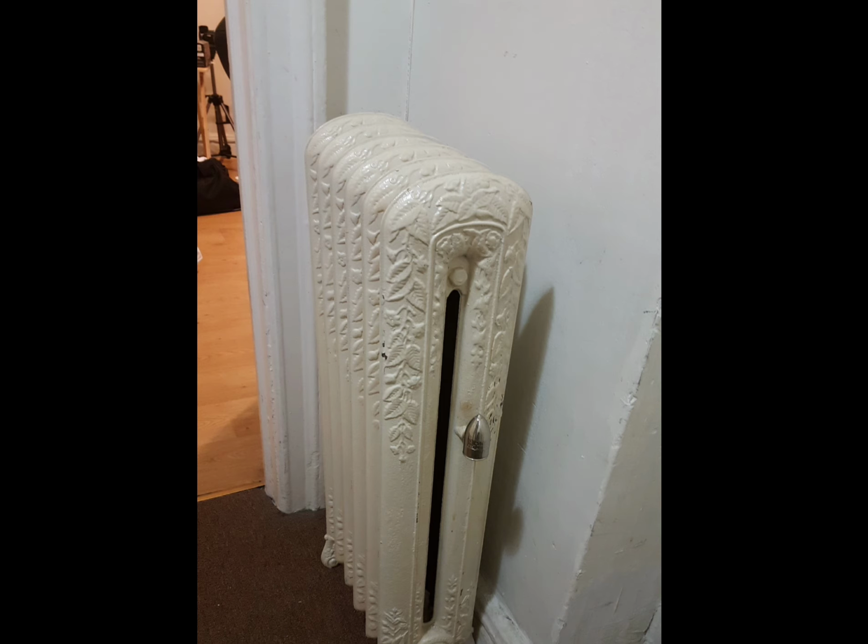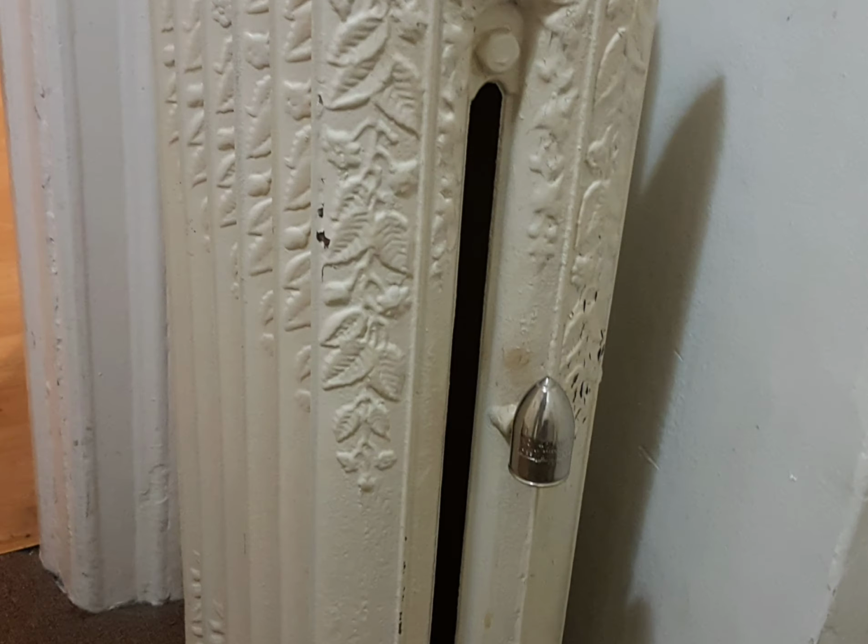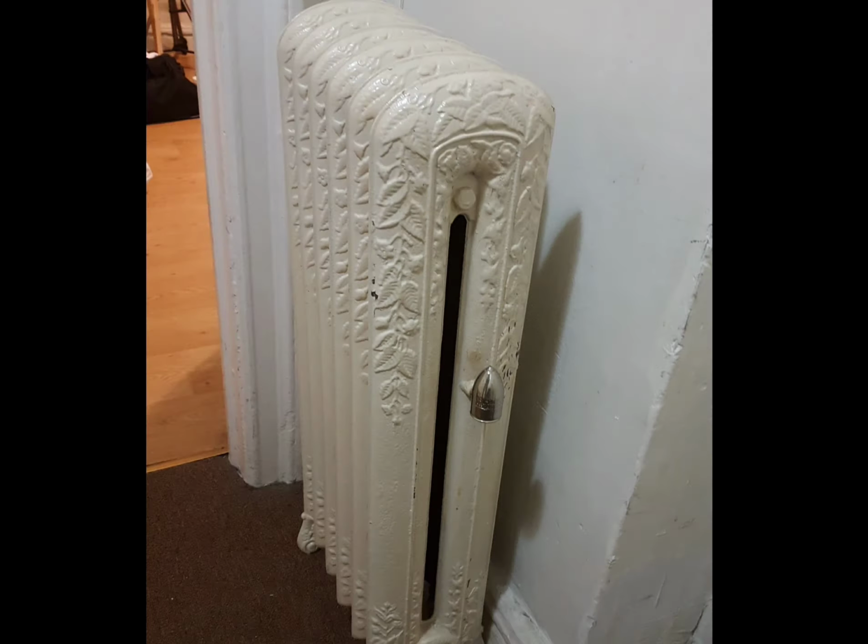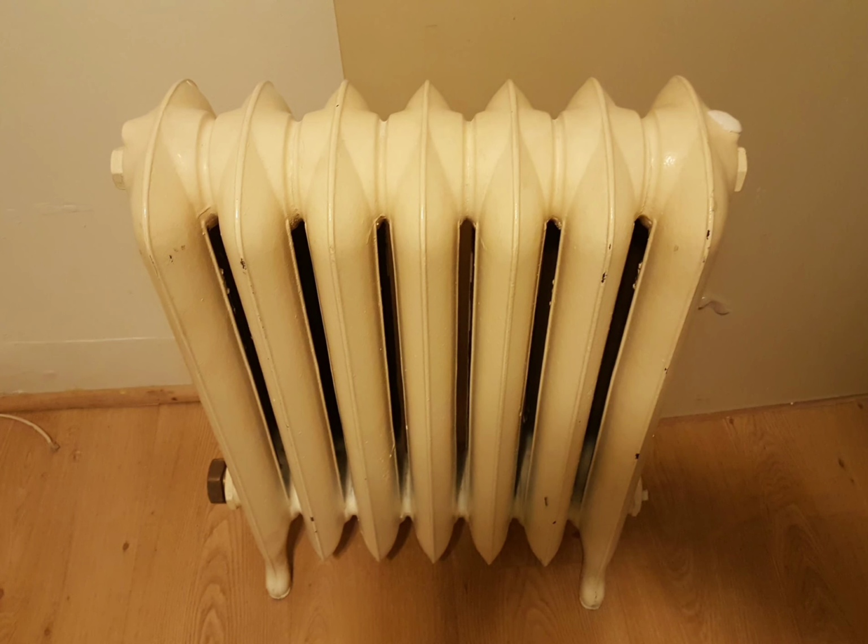Now, on a big building that has a Scotch marine boiler, you're going to hear this vent blowing out air before the steam ever gets into the radiator. You're probably going to hear it blowing out air about 5 minutes prior to steam even getting inside the radiator. Like I told you, the Scotch marine boiler generates a much larger steam capacity, a much larger steam volume, so it's blowing steam through there at much greater rates than a smaller cast iron boiler. And the whole time it's doing this, that's just air blowing through it.